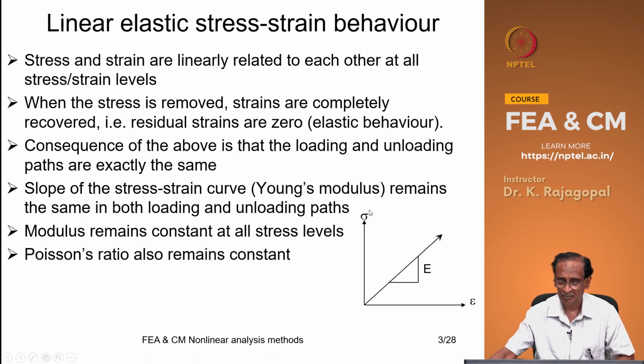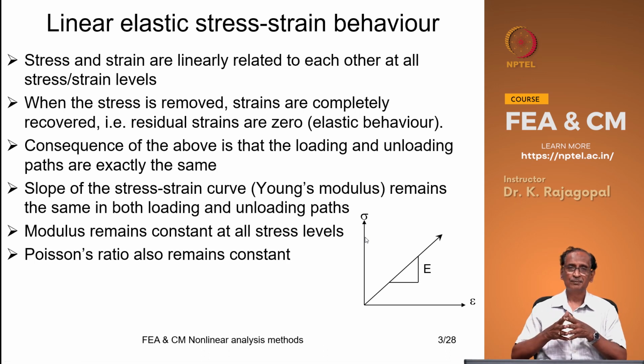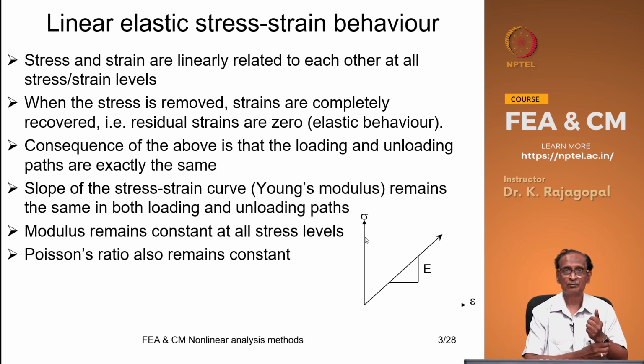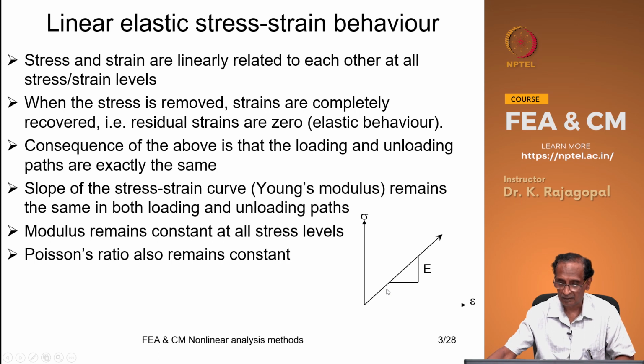And actually here the stress and strain are linearly related to each other. So, that means that whatever loading that you have, you can just apply in one go and determine the corresponding displacements and then the strains, and then of course the stresses, without bothering to go through steps, because our Young's modulus is constant.